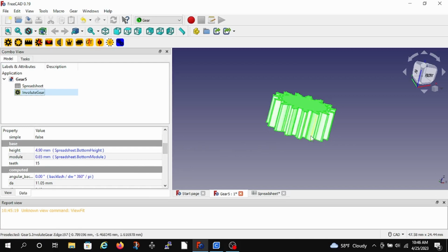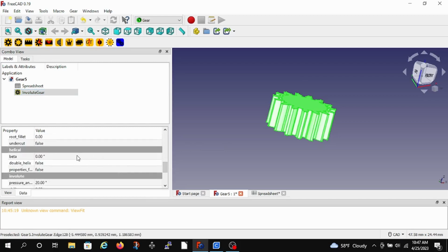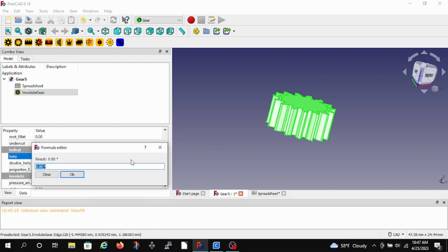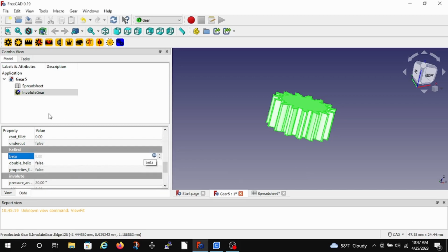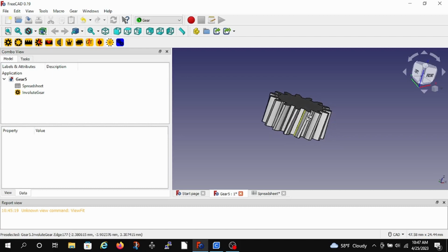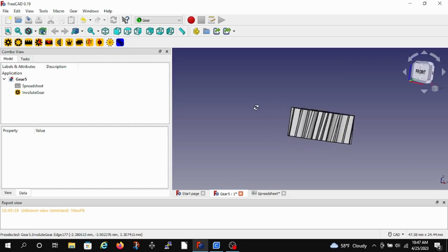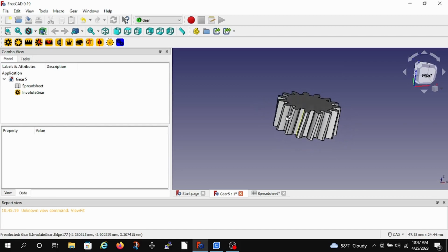And now we've got, these are straight gears. I need to make this into a helical. So this is where we'll put in the value of 8. Helix beta, which I'd rather have it as 7, but it kept changing it. So now we have the helix on the gear. Just a little bit of a helix to mesh up with that worm gear that I need.